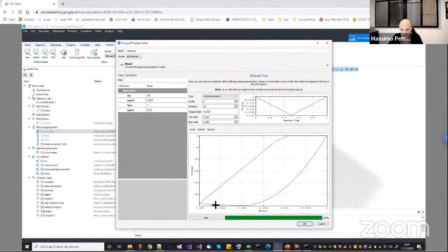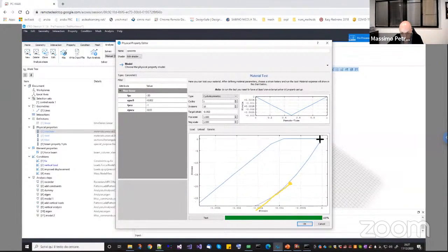The problem is that, in my opinion, the tangent stiffness is fine as far as your nonlinearity is very small, because the tangent stiffness is very close to the secant stiffness, okay? Imagine I'm here. Let me do just a small annotation. I was at 18, so basically here. Now my tangent stiffness is this one in my case, and the secant one is this one.